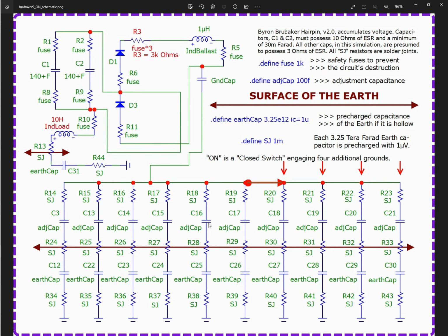I think one guy used polyethylene plastic for his dielectric, and he used 2 metallic plates for his conductive plates, and he immersed them into a vat of oil and shook them and waited a while for all of the bubbles to rise to the surface. I guess it was mineral oil. And then he put a vise, a C-clamp, in there and pushed them together so that the plastic would make union with the plates. But there were no bubbles because he made certain of that. So if there was any residue, it was just a thin film of oil in between the plates and the dielectric. So there are ways of doing it.